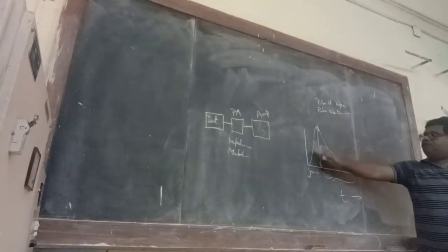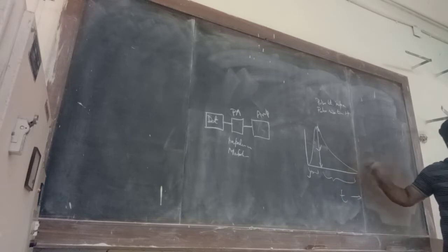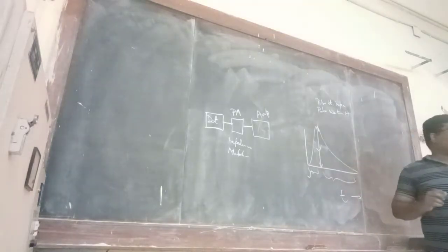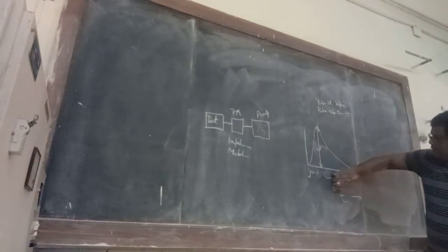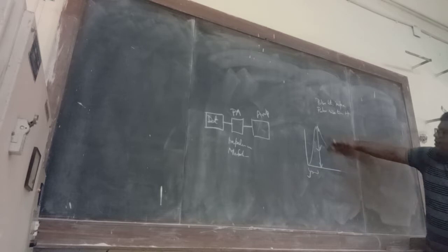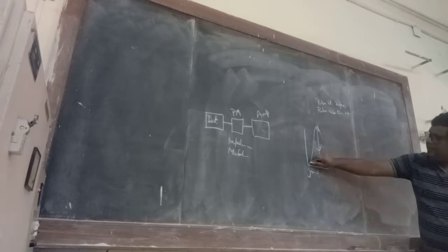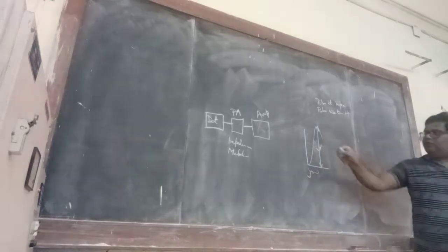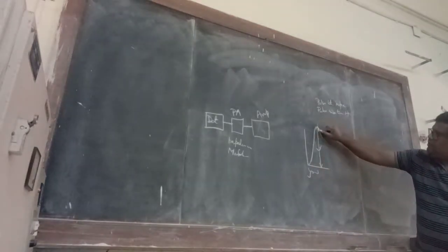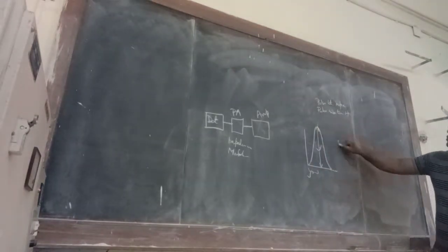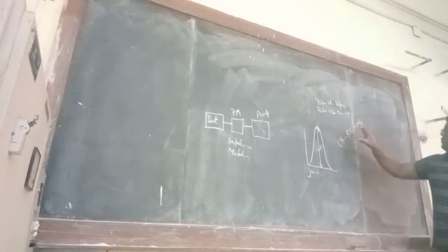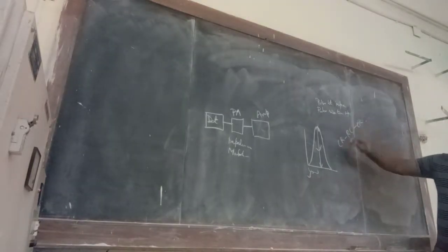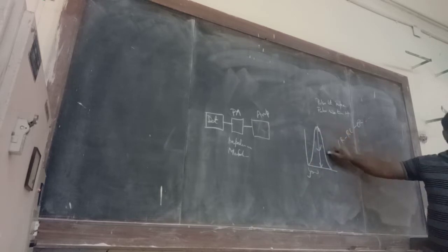So I have to actually measure the entire energy, but for that I have to wait a long period of time, which is a huge time loss. So instead I will shorten this time and do pulse shaping. In reality, this pulse is actually not Gaussian at all. So in this amplifier unit, I will do pulse shaping through a CR-RC-CR type of circuit. Through this type of pulse shaping, I will try to get a Gaussian-like peak.